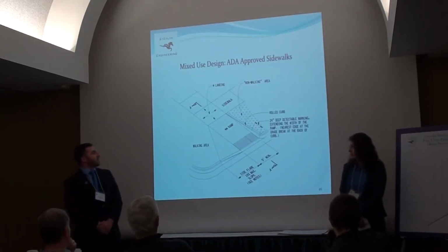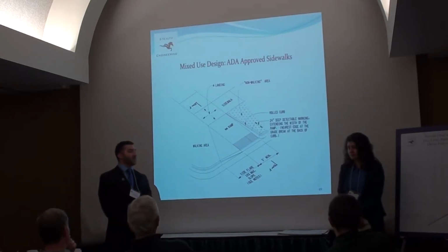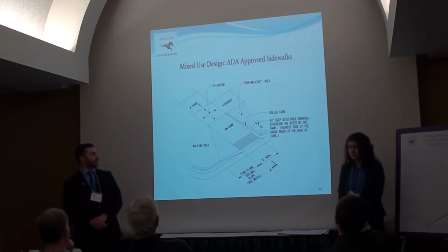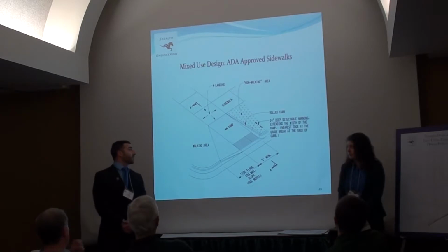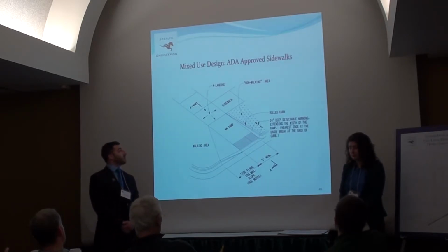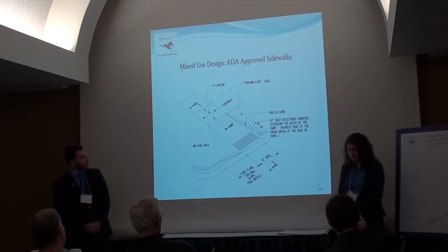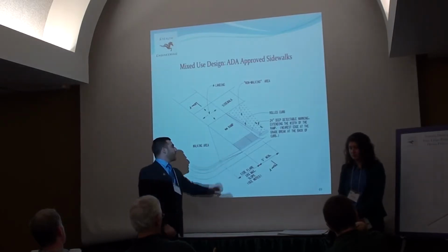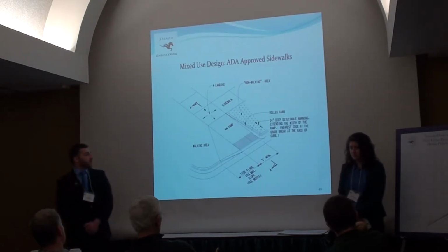Because the pavement specialist elected to go with HMA overlays of all link roads, geometries were to be unchanged. With this considered, it was deemed cost ineffective and not feasible to implement bike lanes into existing link roads. Therefore, we elected to go with sidewalks. All sidewalks will be at least 5 feet across and in accordance with current Americans with Disabilities Act standards. Here we see a typical ramp with a 2-foot long approach, so blind roadway users can detect the ramp.